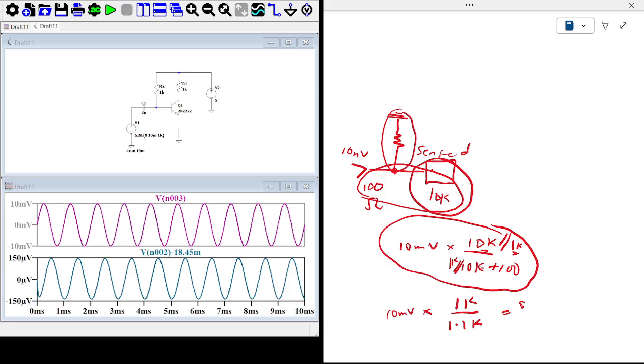So now, for two reasons, I have to increase the value of the resistor R2, which is serving as a biasing resistor. Even though at this point I have the node voltage, you can read the node voltage from down here when I hover the mouse cursor, the probe on this point. It's 779, almost 780 millivolts. That is fine, but then the current that I'm getting from the collector as a result is too high.